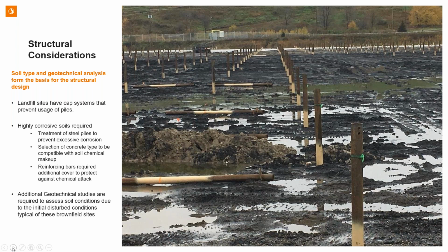In cases where you're using repurposed coal fields, for example, highly corrosive soils may cause premature damage and corrosion to the steel piles, so piling needs to be treated with a retardant. Selection of concrete types must be compatible with soil chemical makeups, and you also may need additional reinforcing bars to ensure that the concrete structures maintain their structural integrity.